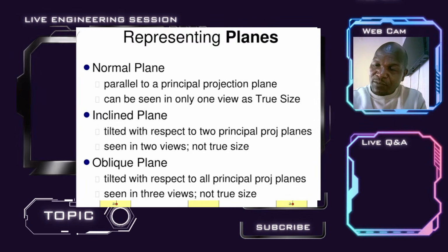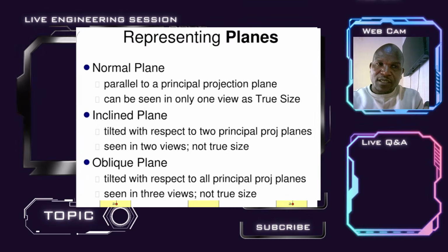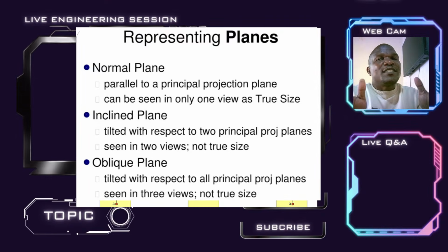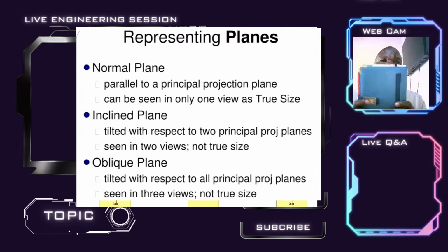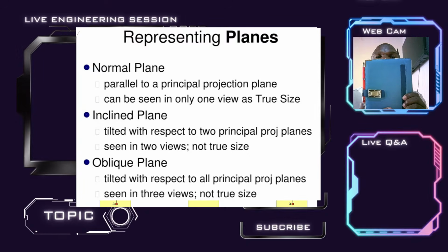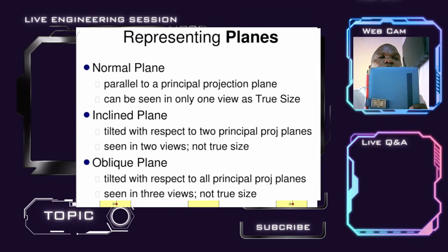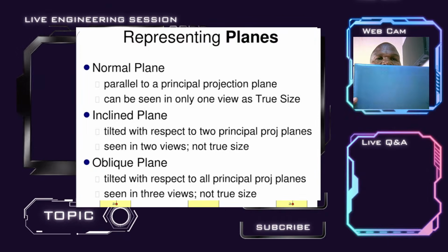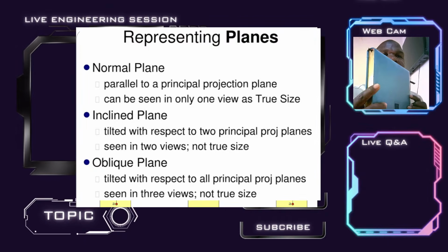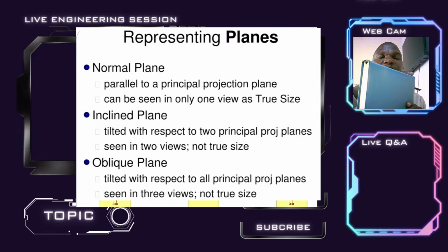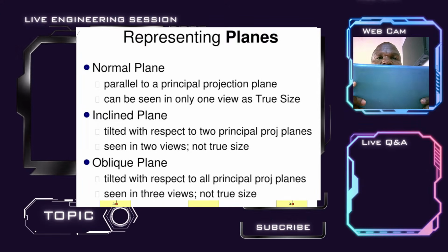If you incline, for example, in isometric projection, this is what we are tilting at an angle. For example, here is this book. If it's directly in front of you, you can just say, a rectangle, right? Let me say this is portrait format, or landscape, what we use in drawing. But if we incline it, can we tell the true length when looking at it this way? No, the true length is distorted in this case. You can't tell it, unless it's directly perpendicular to your line of sight.